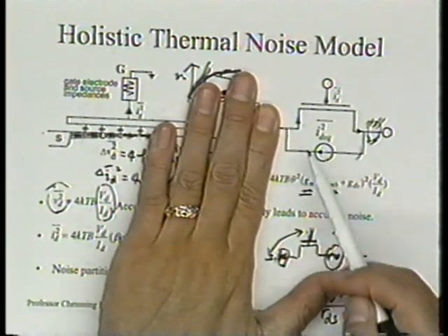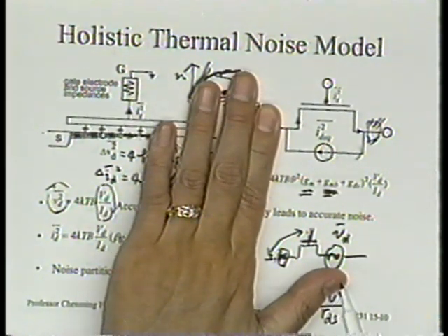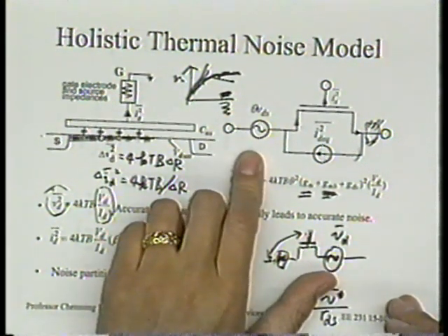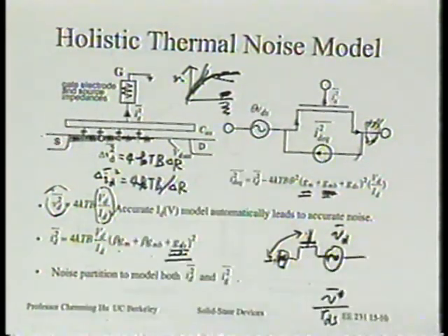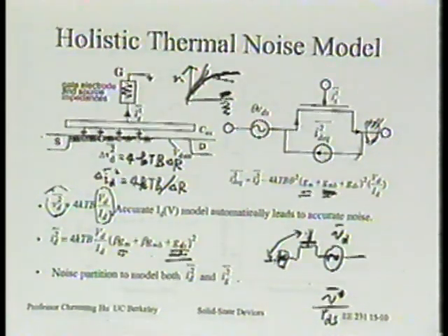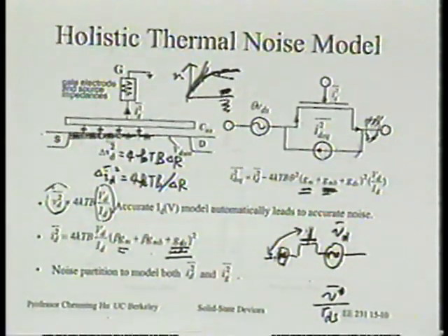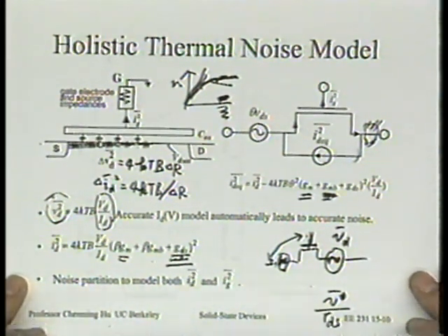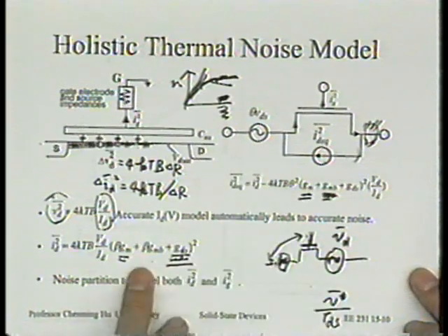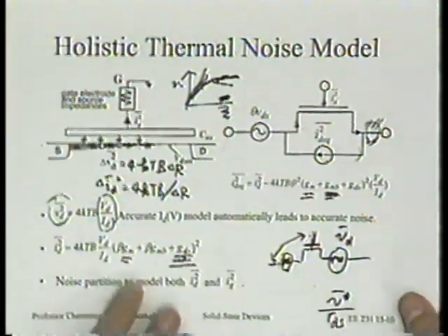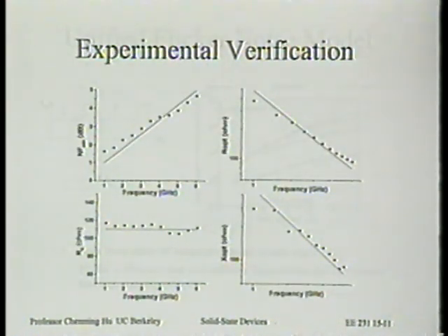They need a model to model the transistor noise in this manner. Up until BSIM4, no one has done it this way, so this is absolutely new to BSIM4. We think this is the right way to do that. So this automatically takes care of the good, accurate GM that BSIM already has. Don't try to express that in terms of mobility and all that, then you lose all the advantage of the good physics in BSIM. So put it in here, and the compact model will take care of GM. All right, so that's the basic concept.